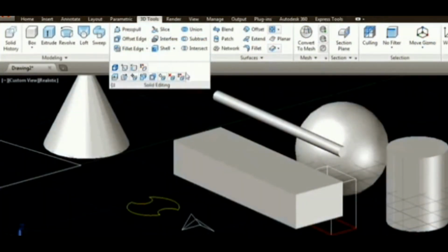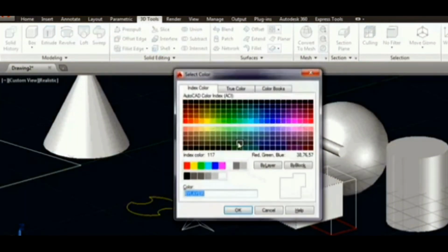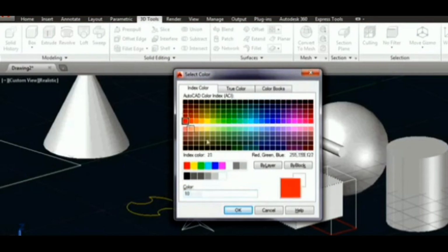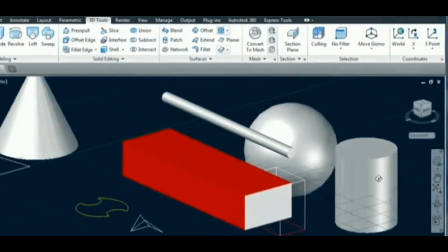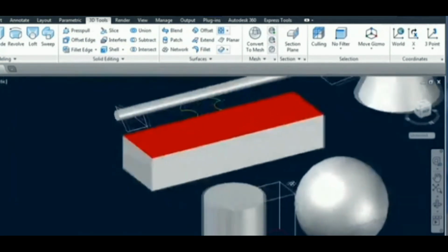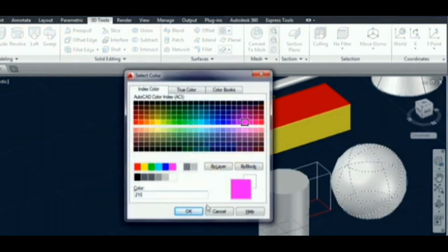You can fill solid faces with colors as well. Go again to Solid Editing and then choose Color Faces. Choose a more rendered visual style to see better the effect. Select the face to change or more of them of the solid chosen. Then press Enter and change the color. This command does work with curved surfaces and so with the sphere too.